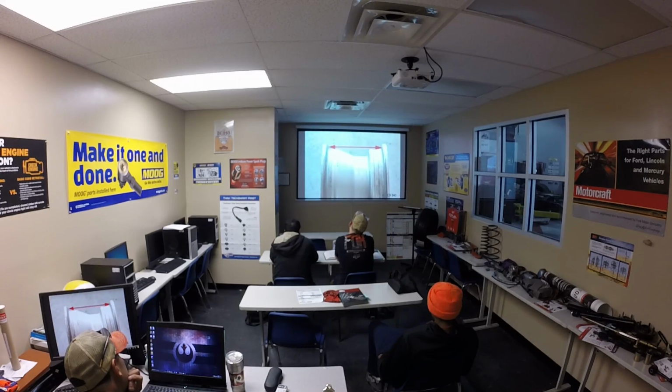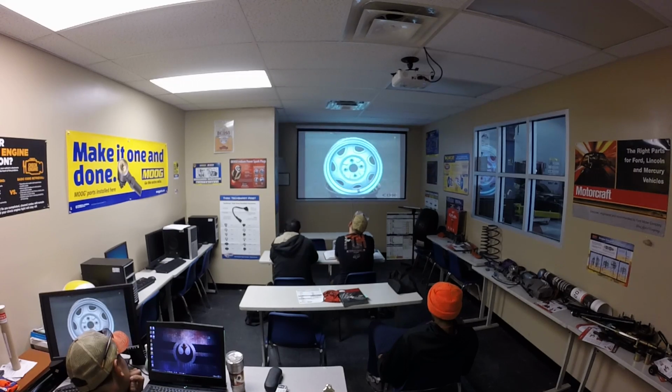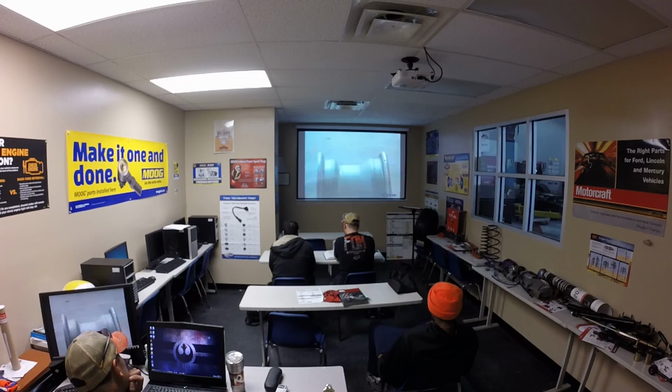The width of the rim is the distance across the rim flanges at the bead seat. Its diameter is the distance across the center of the rim from bead seat to bead seat. The shape of well-based rims is provided by a letter code, such as J, K, JJ, and KK. The width of the rim and the diameter is traditionally stated in inches.